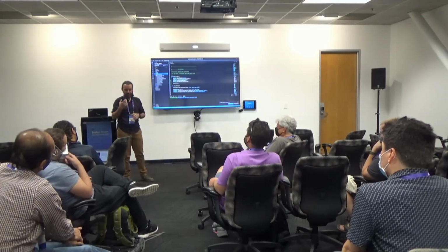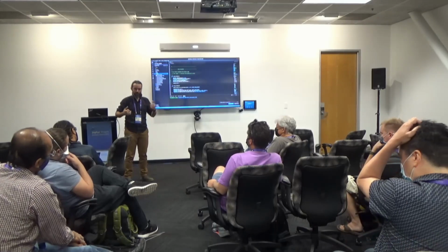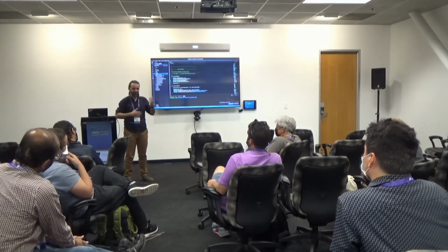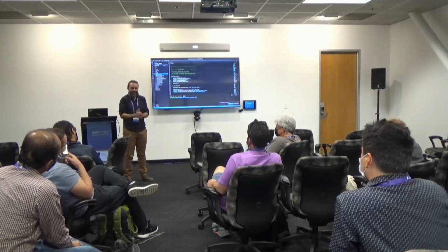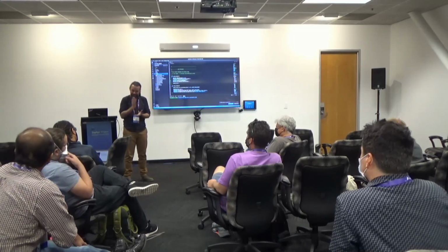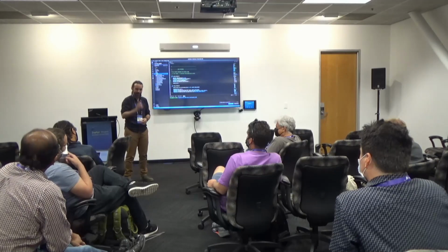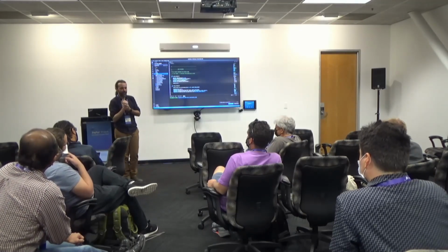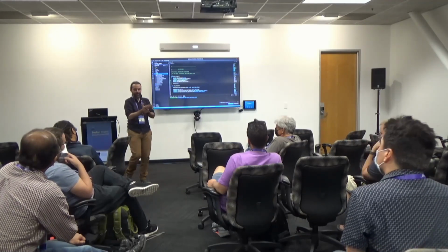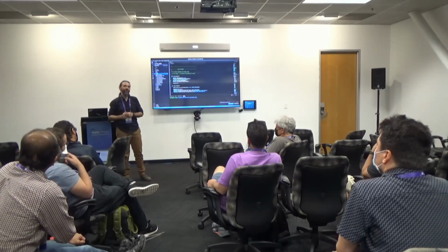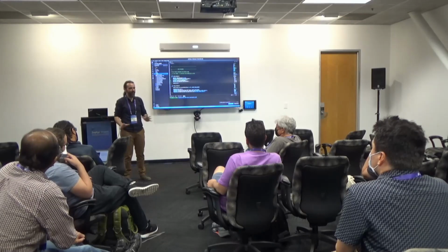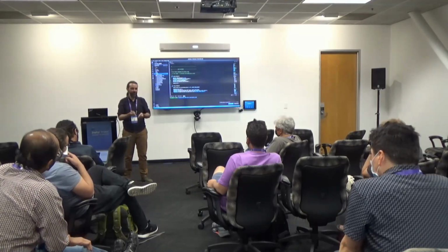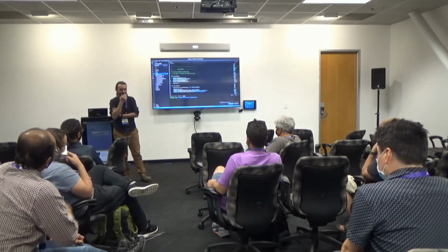You can do workarounds, like a flagging system or cooperative interrupts, but if you have an OS, all you need is to be sure the OS stops everything at that moment to run the single task that needs to be deterministic. That's how we worked around that issue. By using Zephyr, we avoid building a complex bare-metal structure of different tasks handing things to each other. We have one task to handle.